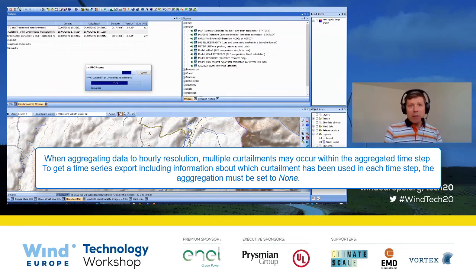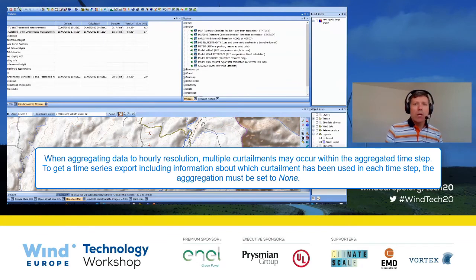And you also have the ability of running WRF on demand from windPRO. In that case, WRF always provides a number of extra data sets apart from wind. That includes Monin-Obukhov length for stability evaluations, atmospheric stability. It includes precipitation, and so on and so on.